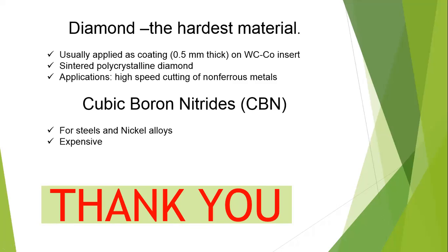The other type is cubic boron nitride, which is similar to sintered polycrystalline diamond. The applications of cubic boron nitride coated tools are for machining steel and nickel-based alloys. Both sintered polycrystalline diamond and cubic boron nitride tools are expensive, as one might expect, and the application must justify the additional tooling cost.